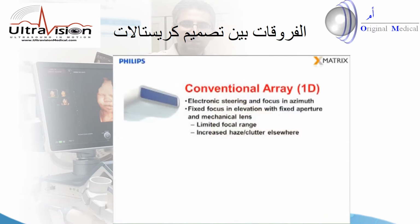A conventional one-dimensional transducer has a fixed aperture and a fixed lens. We want to image in a single plane, but the aperture and lens provide an elevation beam pattern like this. We get good elevation focus, or slice thickness, over a limited range, with increased clutter and haze in the near field and far field. A 1D array can steer and focus within its single imaging plane, but it can't scan a three-dimensional field of view. It can't steer in the elevation direction.